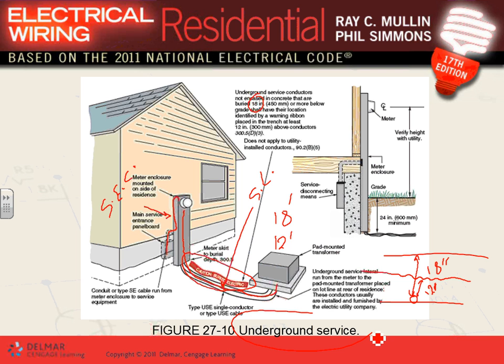The meter, you own and operate. The only thing the utilities will bring to you is the meter itself. The meter socket or box, you will install. You will provide this meter socket. The utilities will decide, they will have a specification. Like Xcel here will tell you, we want you to provide a 200, for example, for dwellings now, you have to have a 200 amp, 240, 120 meter socket, right? That's a minimum that you can provide. Then they will provide the meter itself. Any comments, guys? Any questions?